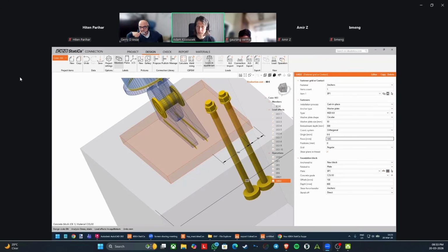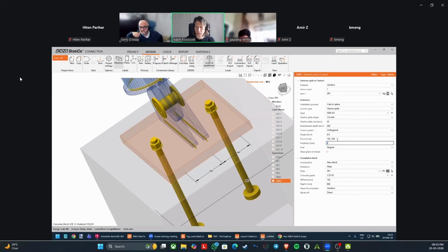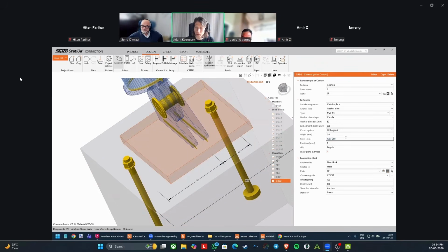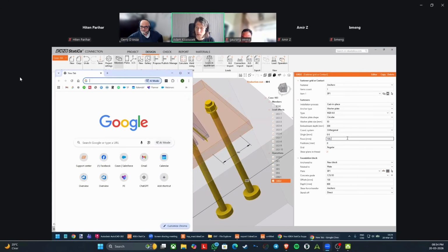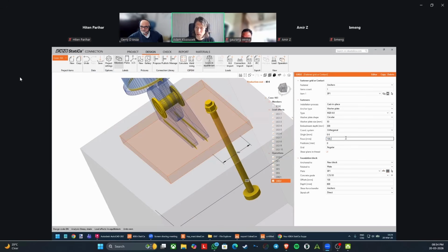So I add such coordinates, so relative coordinates. If I input a semicolon between them, like this, then it's absolute. So this is now another one, which I can move like this.